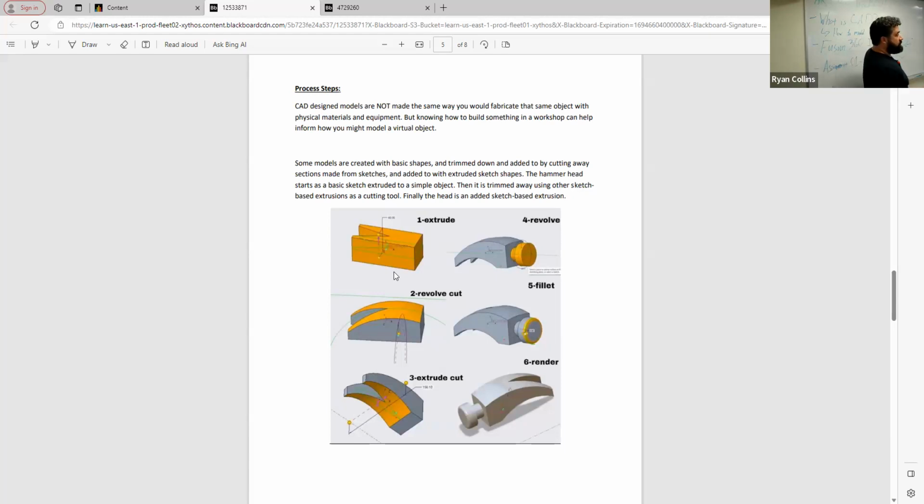And then that's just half a profile, and used a revolve tool, which means literally taking that drawing and turning it in a circle to create a slightly more complex circle with that little stud at the back. That's a really bad drawing. And then use some different tools to round out that front corner, called a fillet tool, not a fillet. Fillet is a fish, fillet is an engineering term. It's a curved surface.